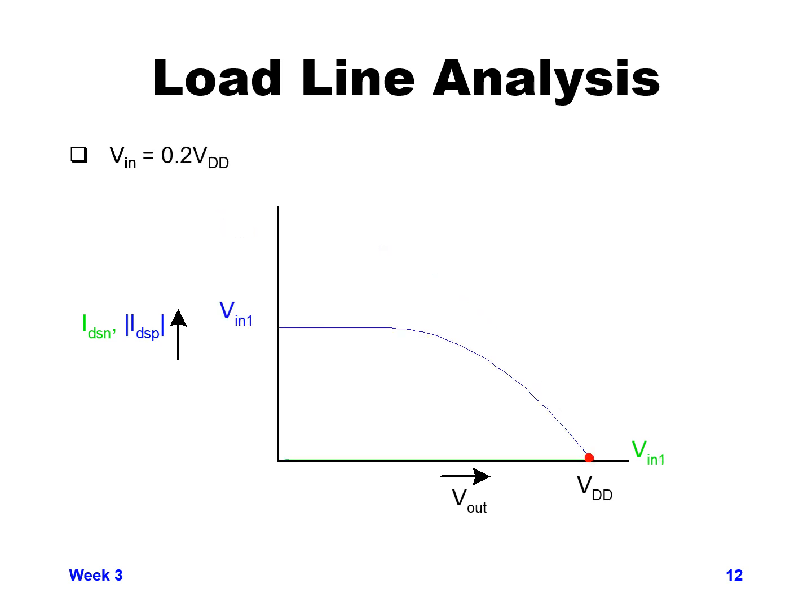So now let's look at if Vn was 20% or 2/10 of VDD. So Vn is 0.2 times VDD. So if our VDD is 5 volts, this would equal Vn1. So if we go back to the previous foil, look at the Vn1 curves for blue and green. The green Vn1 curve was just a little bit higher than 0 current, but mostly a flat line close to the 0 current line.